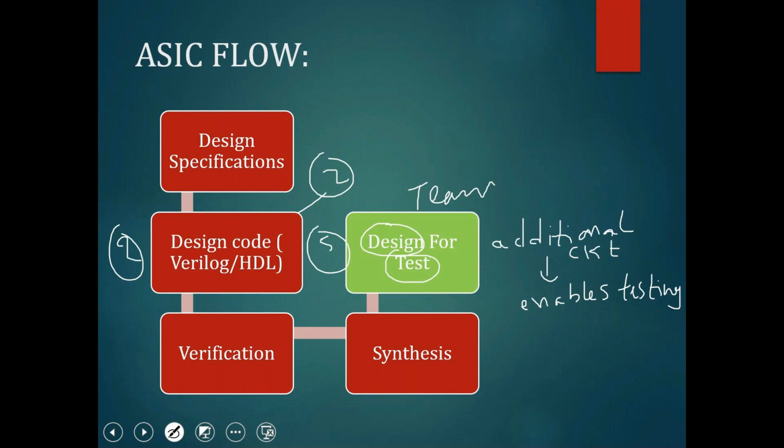So the team has evolved as DFT, alias design for testing or testability. We are responsible for adding additional circuits into the design, into the system, or into the chip, that are required only for testing, which means you're not going to verify or validate any functionality of the chip, whether the chip is working as a divider, a multiplier circuit, an adder circuit or some processor circuit, whatever it is. We are not going to validate that. We are going to add an extra circuit that enables only testing purposes.